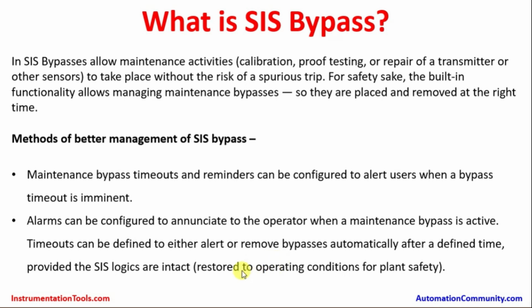Most of the time there are some bypass arrangements in the HMI panel where the operators are doing the operations, like gas detectors in the plant can be isolated by the operations itself just by informing the maintenance engineers or plant automation engineers. Whereas in some cases operations cannot do it; it has to be done by the respective maintenance supervisors or the plant automation engineers or instrumentation engineers who are responsible for the plant area.